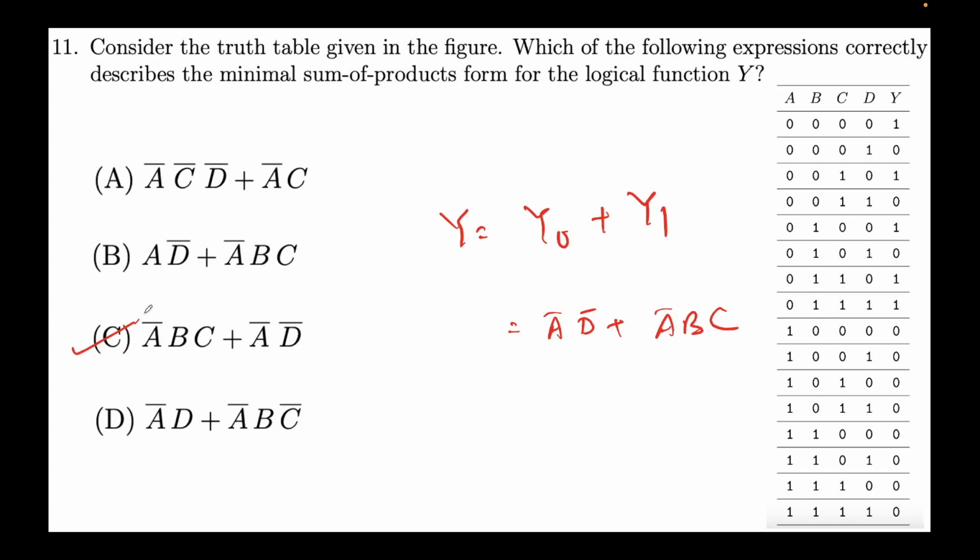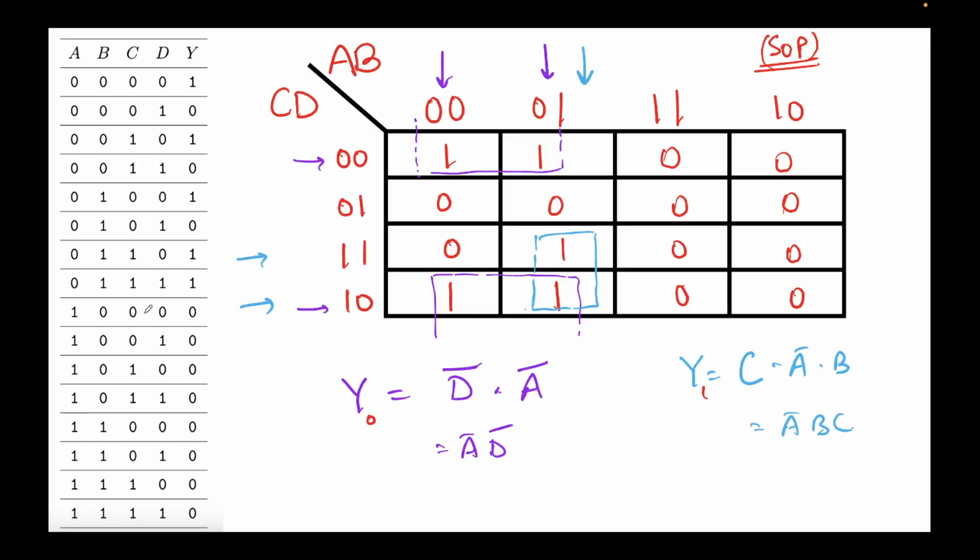Again, fairly simple way, in the sense that you just draw a K-map for this given truth table. We saw in one earlier problem also, we did the same thing. Then we obtained the output corresponding to the purple rectangle, which was A bar dot D bar. How did we do that? Since C is changing, we drop C. D is 0, but we want 1, so hence the negation. Similarly for these two columns, B is changing, so we don't take B, we only take A, but A is 0 and we want 1, hence A bar D bar.